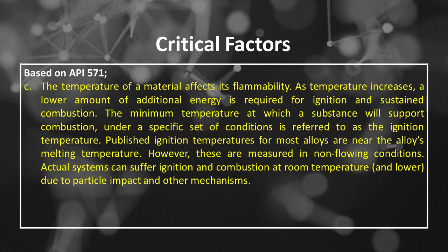Number C, the temperature of a material affects its flammability. As temperature increases, a lower amount of additional energy is required for ignition and sustained combustion. The minimum temperature at which a substance will support combustion, under a specific set of conditions, is referred to as the ignition temperature. Published ignition temperatures for most alloys are near the alloy's melting temperature. However, these are measured in non-flowing conditions. Actual systems can suffer ignition and combustion at room temperature, and lower, due to particle impact and other mechanisms.